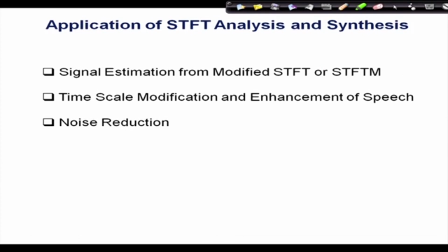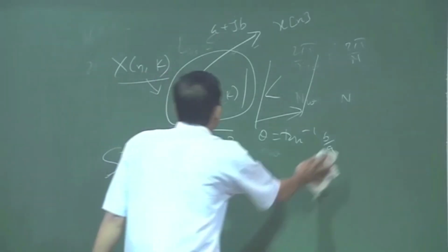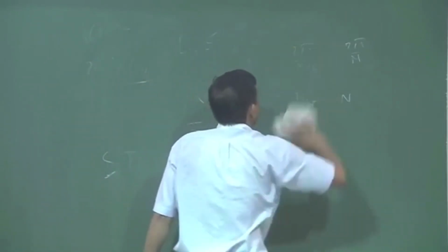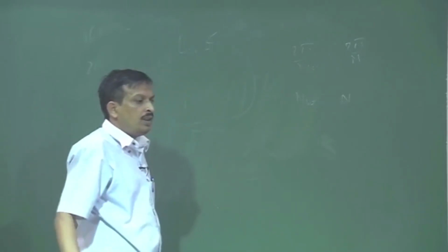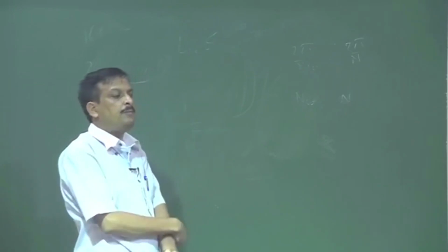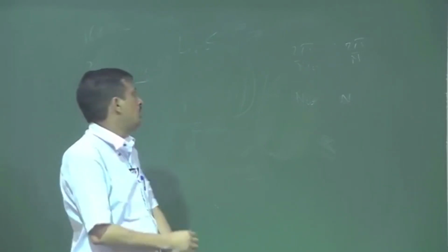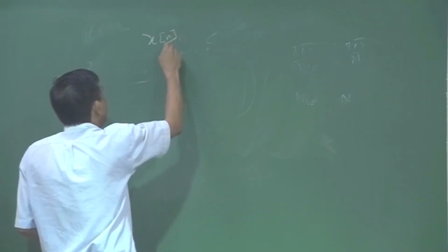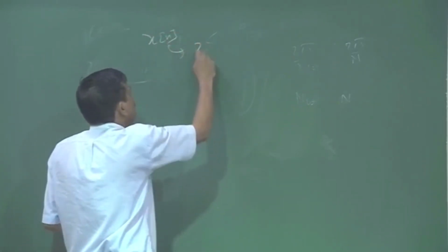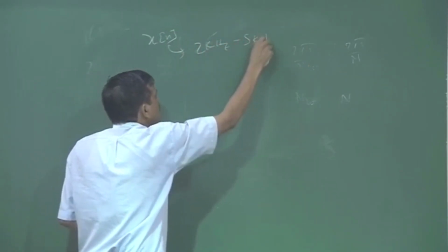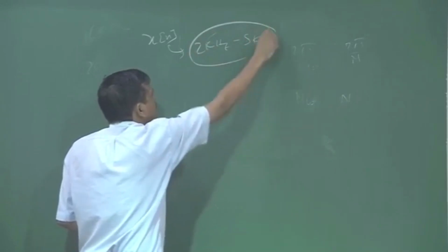So, why do we do STFT? STFT analysis, synthesis, all kinds of things, why will we do it? What is the application of STFT? Signal estimation and modification, with STFT or STFTM both. Suppose I have a signal x[n] that may contain, let us say, a 2 kilohertz to 5 kilohertz component. I want to reduce the amplitude of this portion.